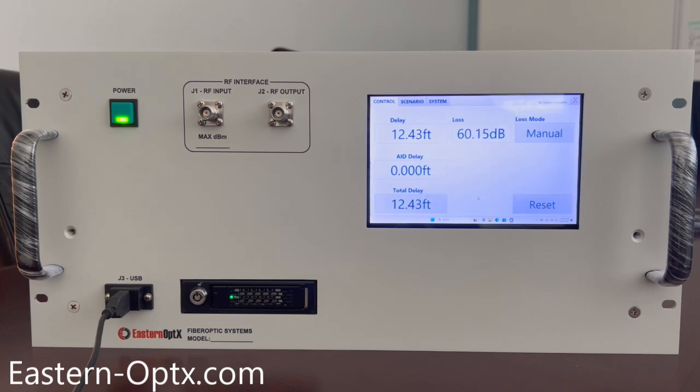Also available is the Antenna Installation Delay, or AID range. This feature allows the user to duplicate the delay associated with the aircraft cabling between the altimeter and the antennas mounted on the underside of the aircraft. The AID range is approximately 500 feet, and when used, can allow operation down to the 0-foot altitude, including test cables.